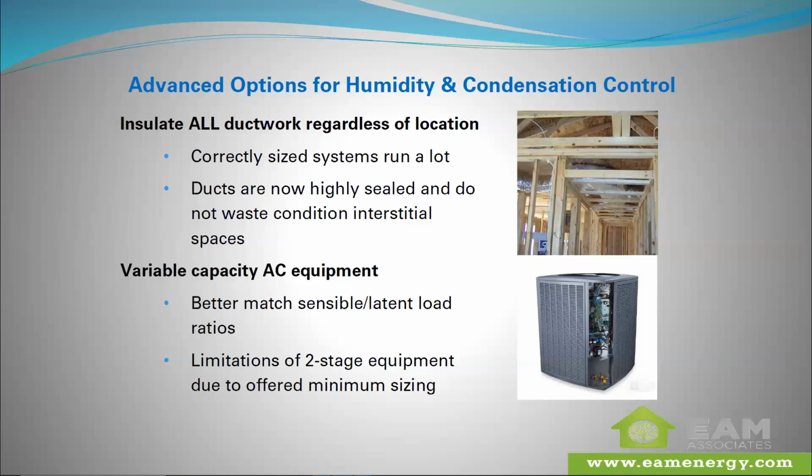Most of your two-stage equipment, the minimum sizing goes up to 2 tons. So where you could get 1.5 ton equipment in the smallest size in your basic single-stage equipment, you're not going to be able to get that. And so that 2-stage equipment, when it ramps down, it's just going to go back to that 1.5 ton.